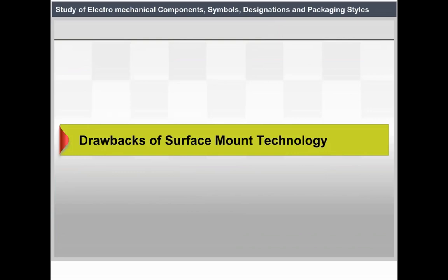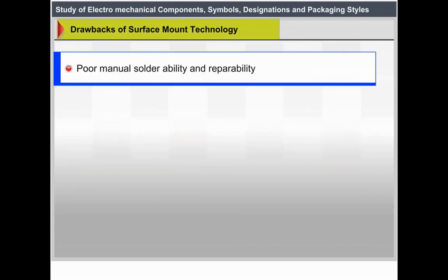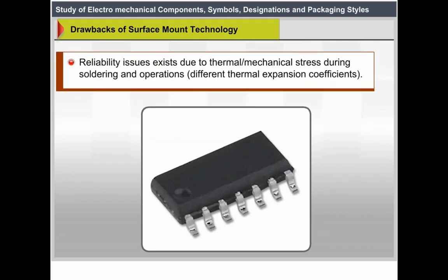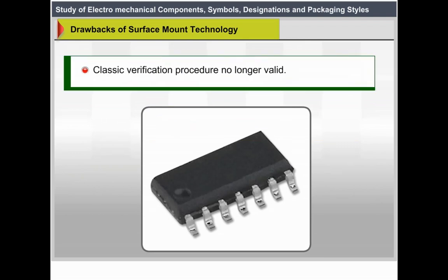Drawbacks of surface mount technology. Poor manual solderability and repairability. Reliability issues due to thermal and mechanical stress during soldering and operation. Different thermal expansion coefficients. Classic verification procedures are no longer valid.